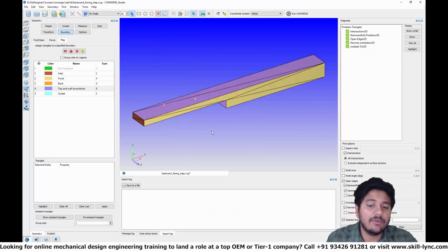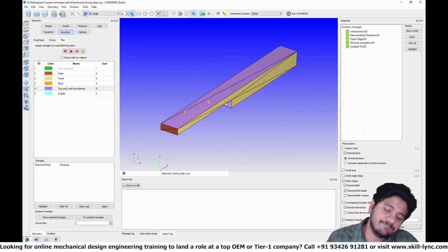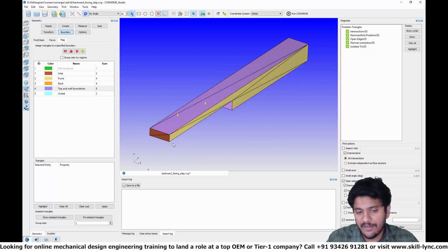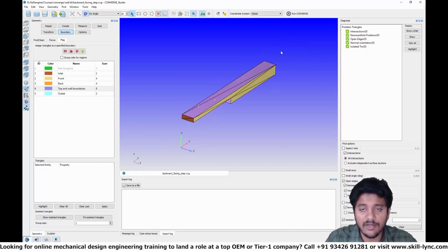So the type of simulation that we are going to be doing here is a 2-dimensional simulation. All right, so why are we doing 2-dimensional? Well, in the experimental data, the dimension along the z-axis is so large that you can actually think of this as a 2D problem. So there is no variation along that axis. And for a 2D problem, obviously you can use more number of cells.